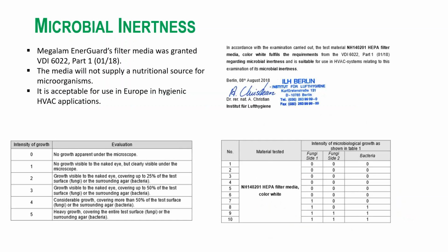Again, if we're working with any type of biosafety or biocontainment space, we definitely want to talk about microbial inertness. Generally, if we're working with a bacterial vector and we have anything else growing in the air handler or growing in the space, it just makes it that much worse. So what we want to see is that the media is not promoting the growth of any type of microorganism, outside, especially, or inside.